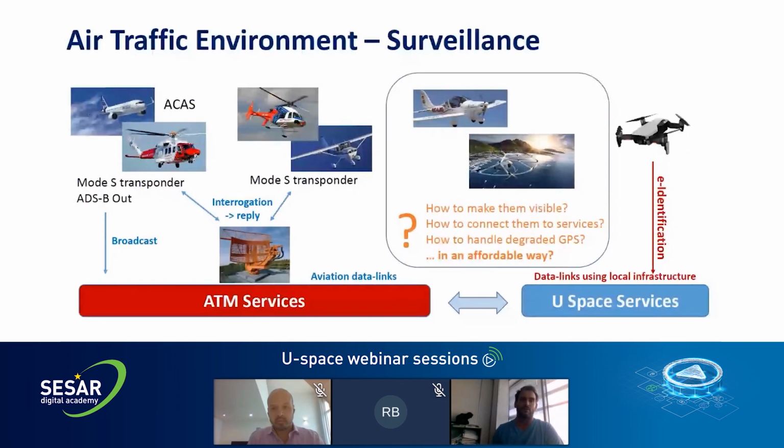On the other hand, we have the new type of users, for which the new regulation related to air identification and position reporting is under development. And then we have ultralight aircraft, sport aircraft, so a big part of general aviation, and also rotorcraft, which do not have a transponder. These are not drones, so they are somewhere in between, and they represent a potential threat for both types of user, because the only way to detect them is through visual contact for manned aircraft, or through some kind of non-cooperative sensors, for which the performance is usually lower than on cooperative surveillance means.